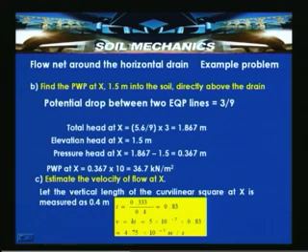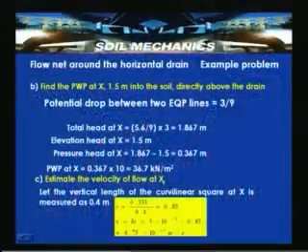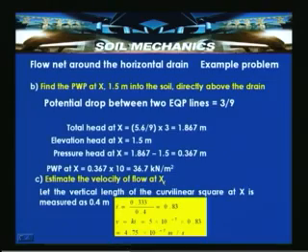If you know exactly where the pore water pressure is required, then from this construction we can estimate the head at a particular point. From there, by looking into the elevation head, we can calculate the pore water pressure at a particular location. So this is an example which demonstrates it, but by using the same concept, we can determine the pore water pressure at different locations. Now estimate the velocity of the flow at X. So we are also asked to determine the velocity of flow at that location X.